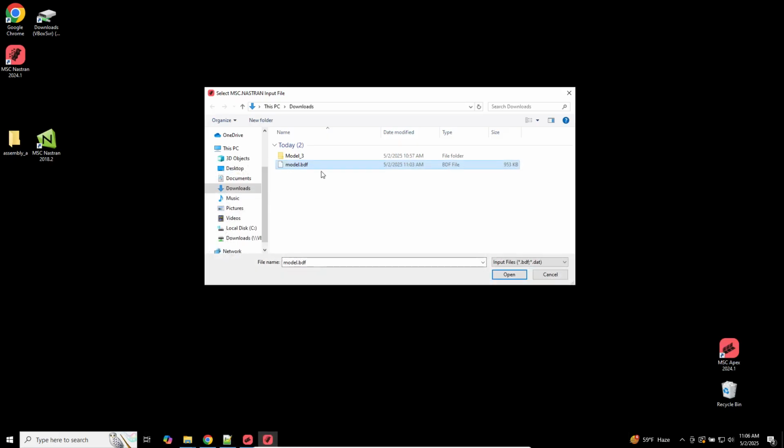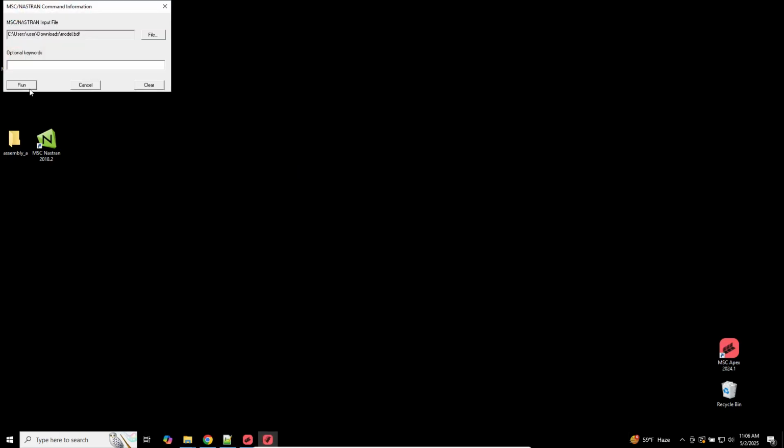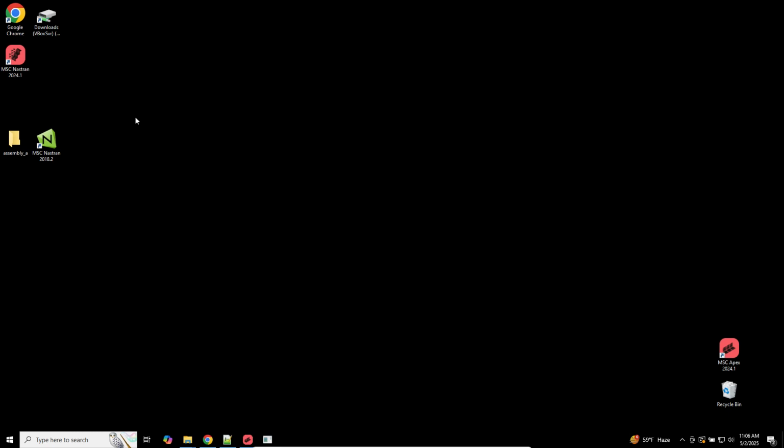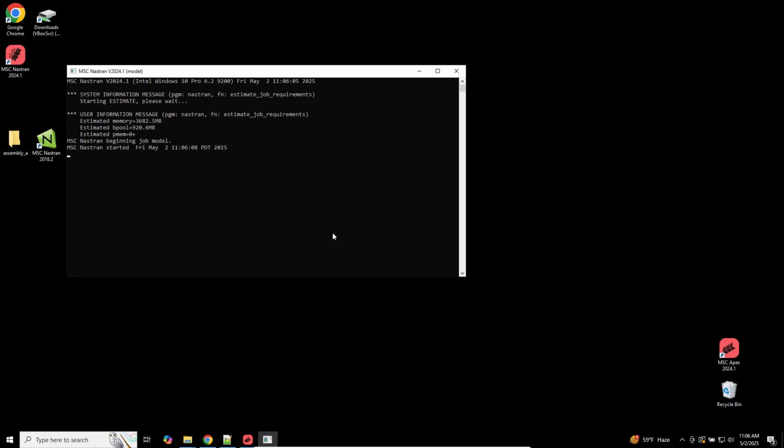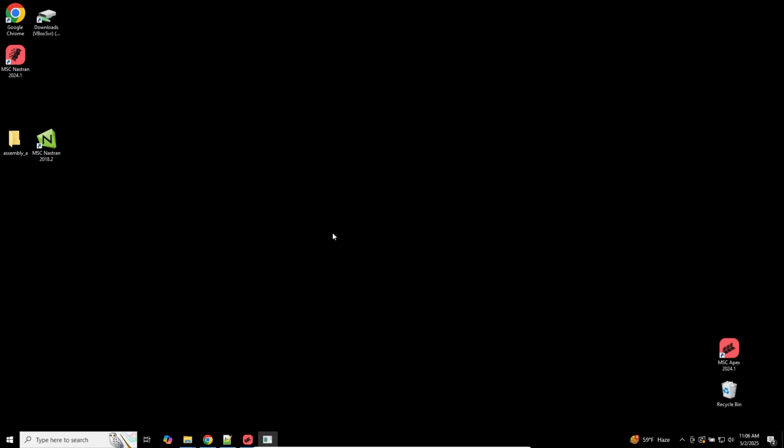Here, what I'm doing is I'm telling Nastran, hey, take that bulk data file that contains my finite element model of the whole cylinder, perform, at least for now, a normal modes analysis. Now, why am I doing a normal modes analysis? You would use this when you're performing maybe a vibration analysis, maybe you're interested in dynamics. But one very good thing about normal modes analysis, it can tell you if you properly supported your model.